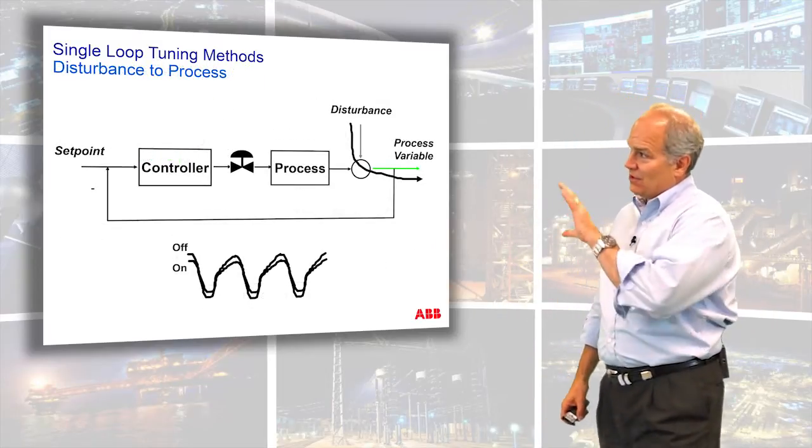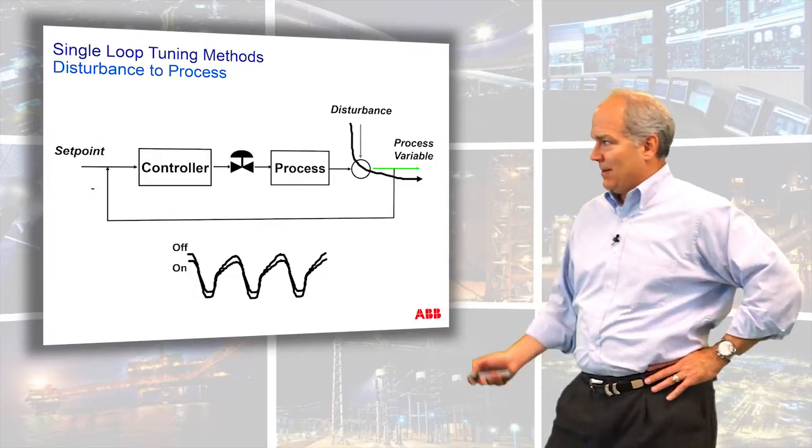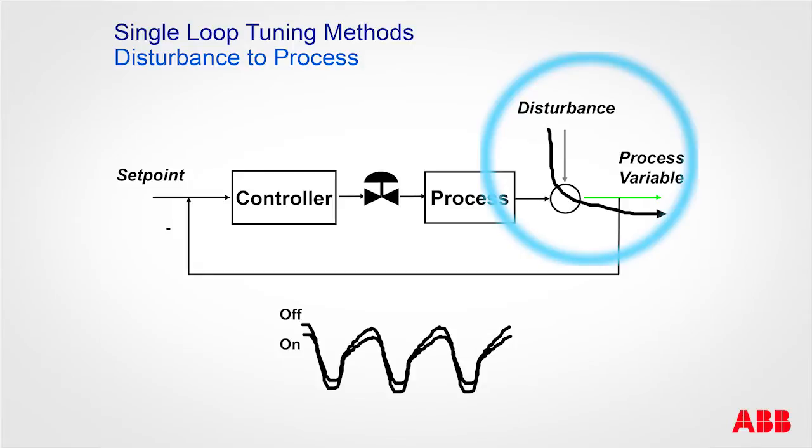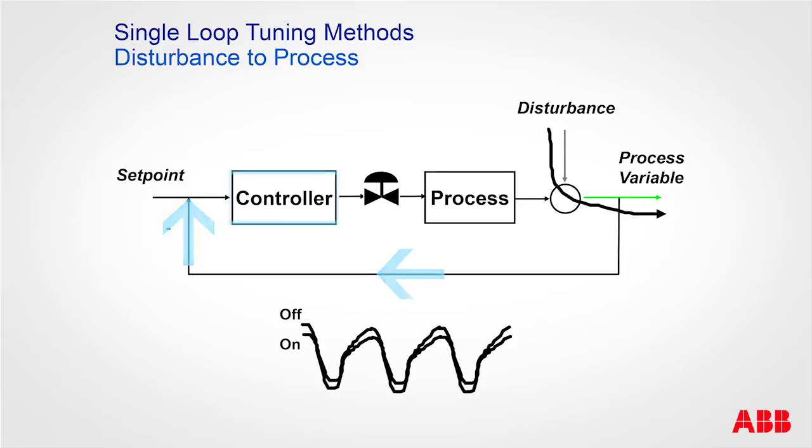So this picture also kind of illustrates what's happening with the disturbance. Remember, this is a feedback control system. So this actuator has to move fast enough to counter the effect of this disturbance. If the disturbance is affecting the process, it has to generate an error. Then the controller has to think about it and make a change in the actuation device. If this disturbance is oscillating too fast, this thing can't adjust the actuator fast enough to stop the disturbance.